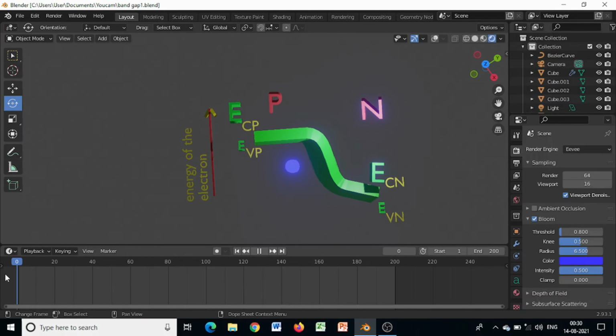Electron initially was in the occupied valence band, from which the electron tunnels, and also allowed empty states should exist on the other side, into which the electron penetrates at the same energy level. Look at this, at the same energy level. That is very important. Only the thickness of 100 angstrom or 1000 angstrom is a requirement, but not a sufficient condition.